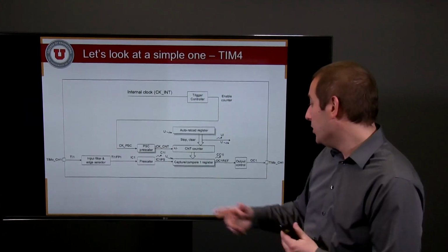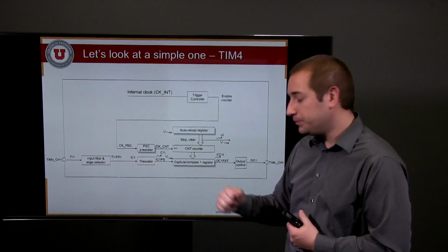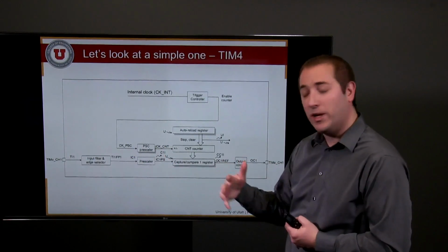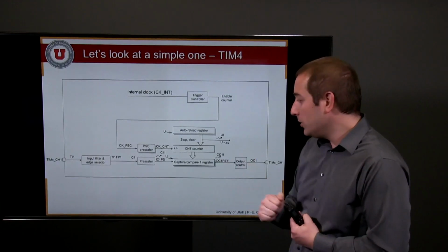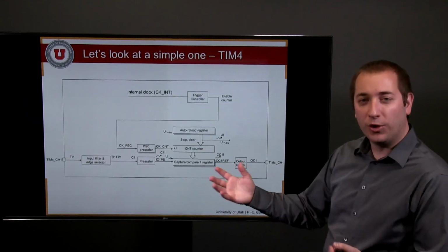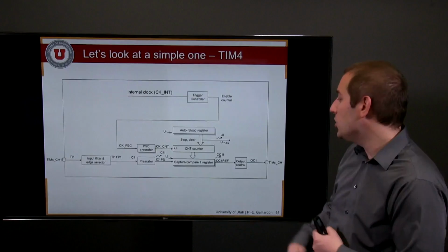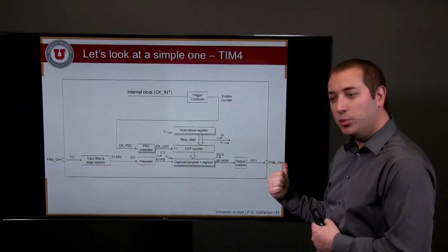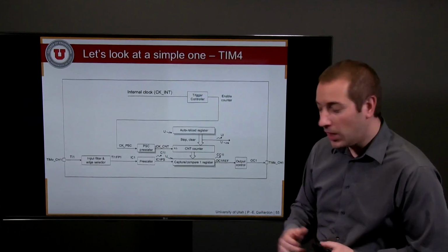external triggered input. And once you have that, you will be able to either count what's going on outside and generate specific interrupts, or also you'll be able to compare with the counter, decide when to stop, generate interrupts, or also at the same time you will be able to create output value and periodic signals.